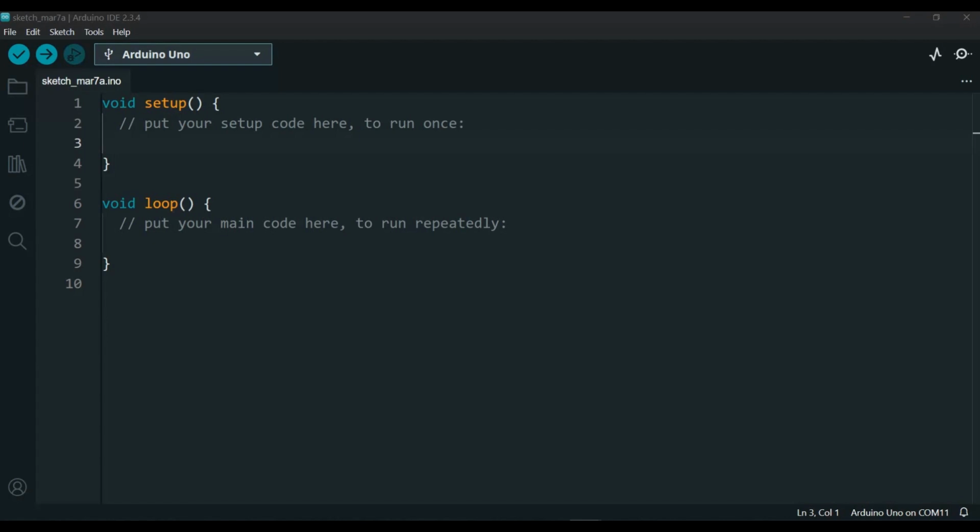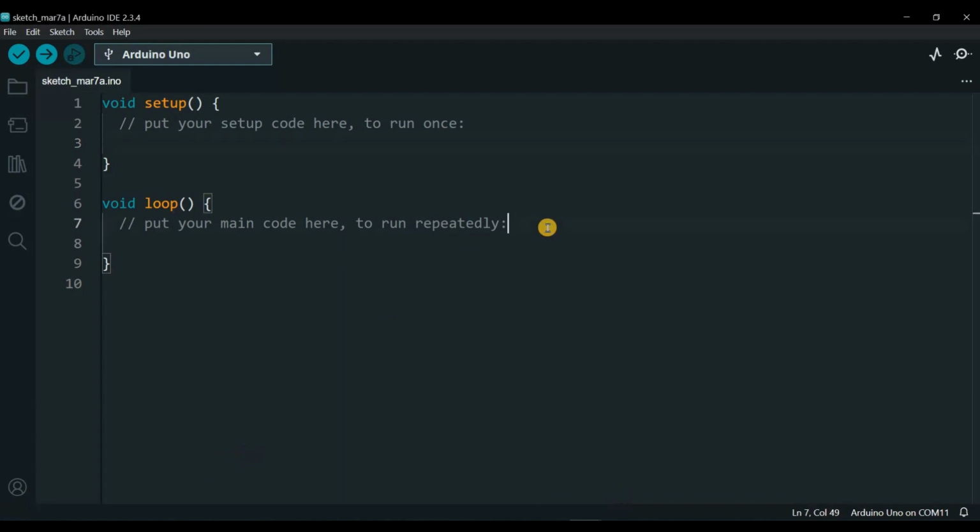So after we know which pins support the hardware PWM, because sometimes we can bit bang it. Let's say if all the PWM pins have been used already and we need more, we can use a bit bang, or we software emulate the hardware, but this is not the topic of this tutorial. So after we declare and know which pins we are going to use as PWM, you'll be surprised how easy it is to output the PWM to the pin, which can be done in only one line.